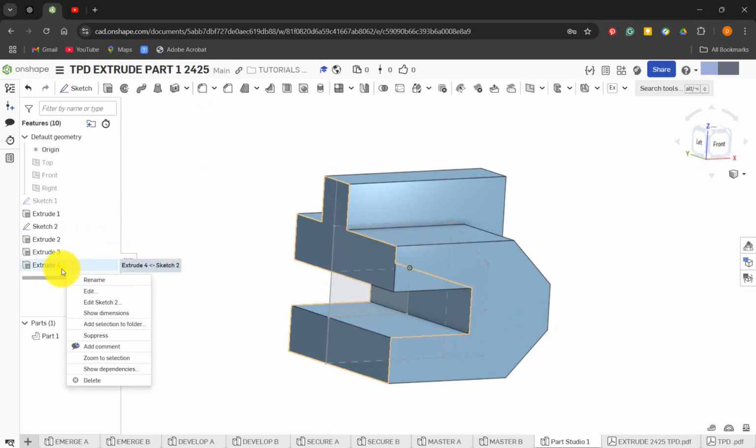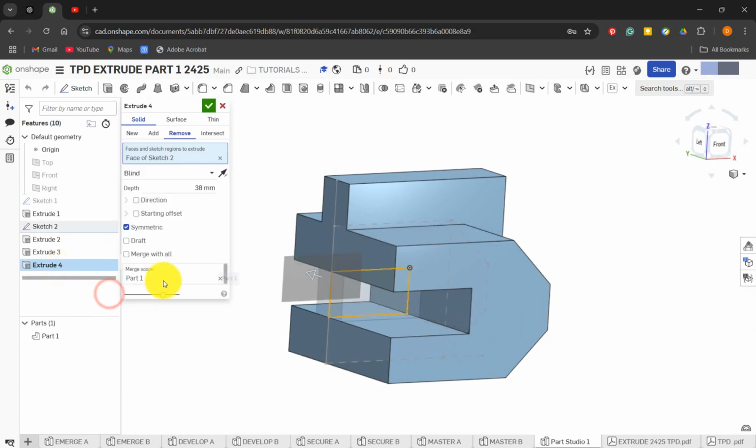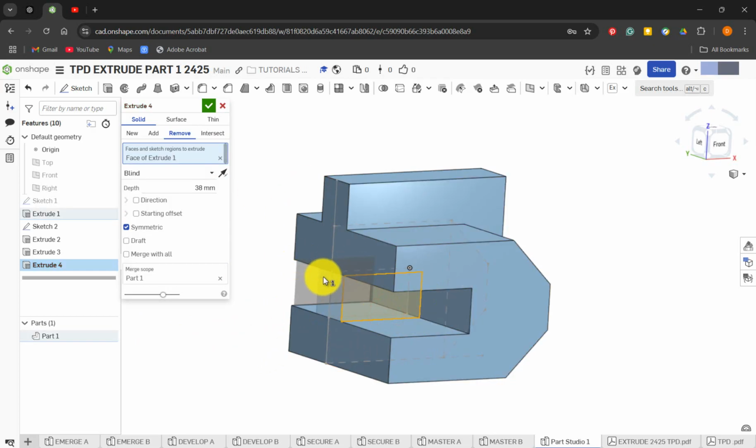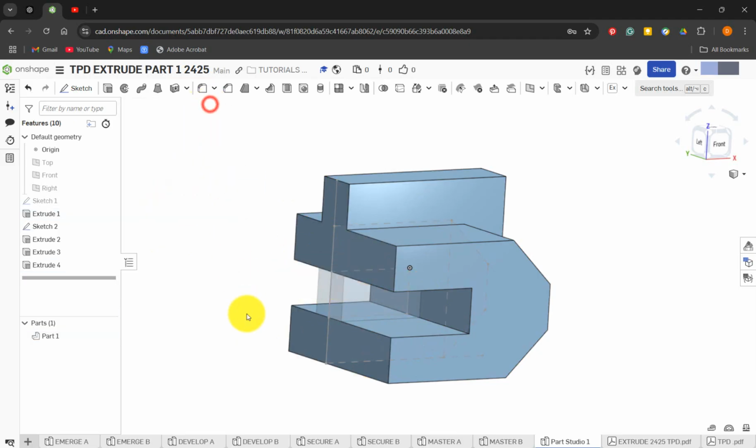But the way I want to show you how to do it is you don't have to use the sketch. So I'm going to get rid of the sketch, okay, and I would do this anyway. I wouldn't bother trying to hide this selective one. I was just going to literally click on that and drag that across as long as it's going past the object, and delete it. So I've used the face this time to create a feature which I've then removed.